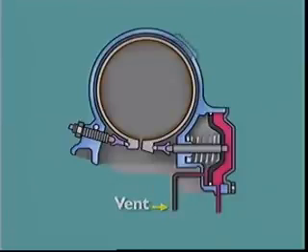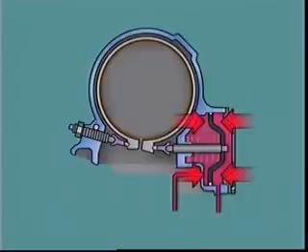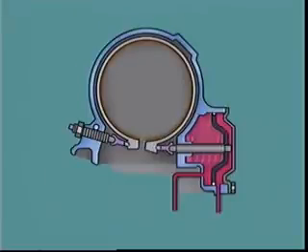Release is obtained by supplying fluid at the same pressure to the opposite side of the piston. As soon as pressure is equal on both sides, the piston is moved to the release position by the force of the return spring acting on the release side. The band speed of application or release is controlled by the rate at which fluid on the release side enters or leaves the servo.